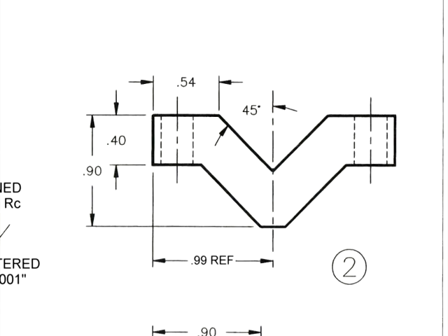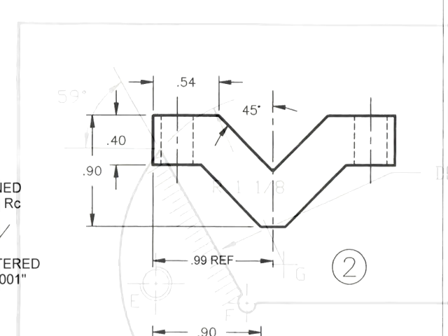As previously mentioned, extension lines are fine lines that don't attract attention, and they come close to but don't touch the contour lines. This helps to clarify the boundaries so that you don't confuse an extension line with a contour line. Sometimes extension lines aren't required, and sometimes a center line can be used as an extension line.